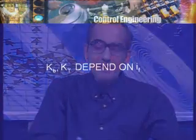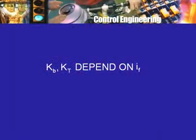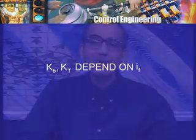The assumption that I was making is that I know KT or I know KB for the motor, but if you remember, I mentioned earlier that these constants, the back EMF constant and the torque constant, both of them depend on the field current IF. So in fact these two constants are determined by the field current. So when I say I know KT and KB, what I really can find out is, for this field current, what should be KT and KB.